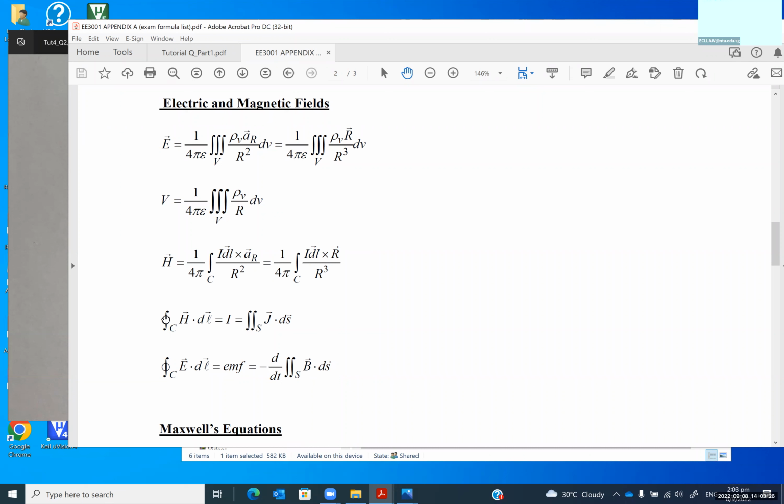So what creates the loop? There are two terms there, right? There's the H and there's the dl. Is it the dl that creates the loop or the H that creates the loop? dl is the one that creates the loop. You choose a path that you want to go around and come back. That's your dl path. Do you want to go around in a circle and come back? Or like a triangle? A square? An oval? An arbitrary shape? Which one?